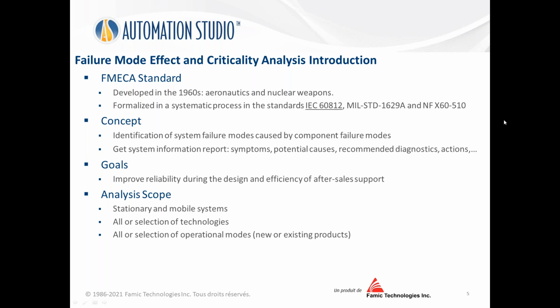And the concept of the FMECA is finally to identify all the system failure modes that are caused by component failure modes. So we talk about components that participate in the architecture of the system. At the end of the analysis, we get a system information report with qualitative and quantitative information that will be useful first for the design department in order to improve reliability of the system, and for after sales support to make the support efficient when troubleshooting occurs in the field.